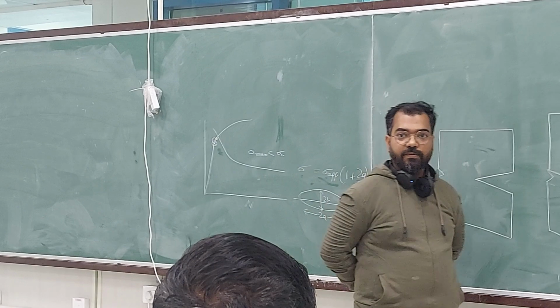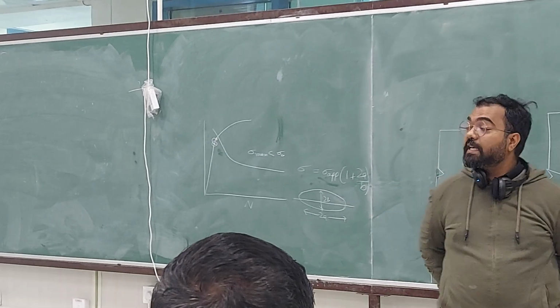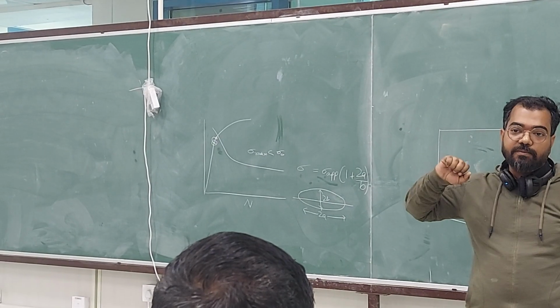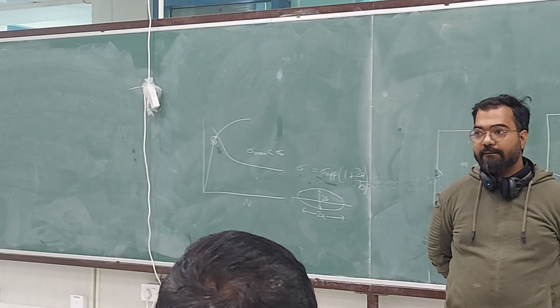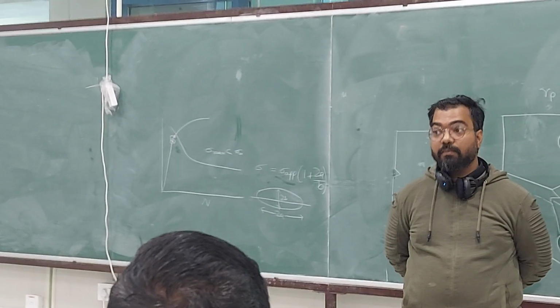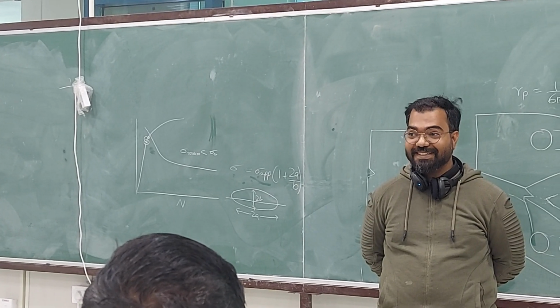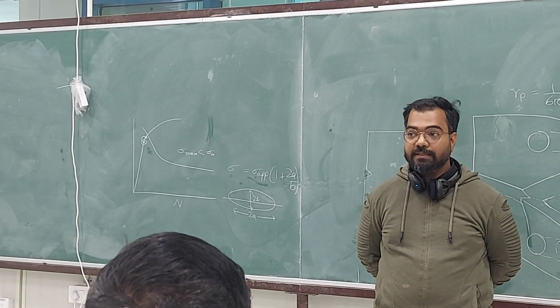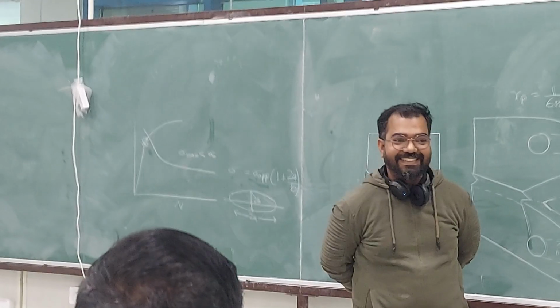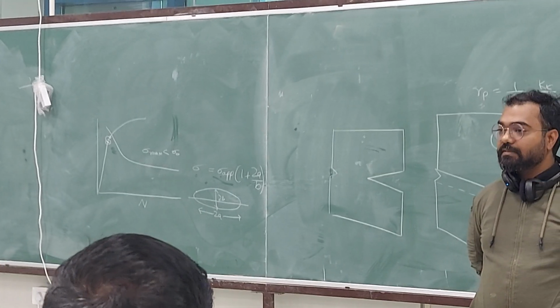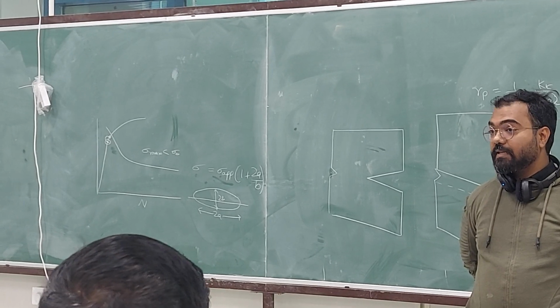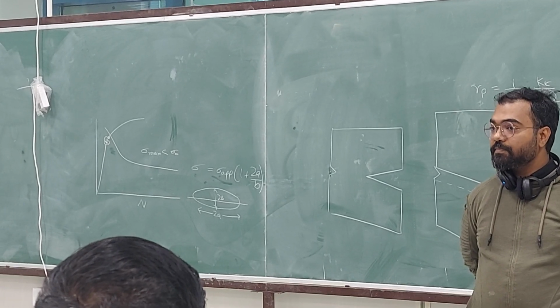So the stress amplitude will be given by sigma max and sigma min. Sigma max is not going beyond sigma naught, so what difference does the amplitude make? Because plastic strain is always there, as you told earlier. Plastic strain is always there. That is correct. And people have done experiments.